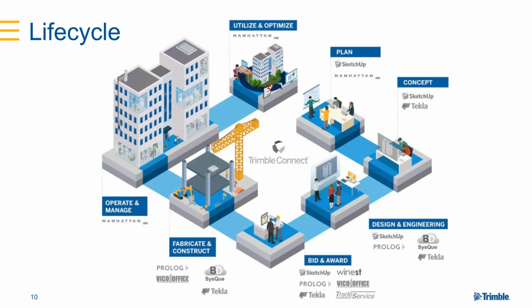So what I don't like about this slide, it fails to mention Trimble Access and Trimble FieldLink and the role of the surveyor. So I really want to stress the importance we as surveyors have in this project lifecycle. Before the design can even start, you have the surveyor on site collecting current topography or building as-built. Sometimes even during the proposal stage, you have surveyors doing some quick measurements or data collection for preliminary design. During the construction process, we are present for staking out and quality control and verticality checks and floor flatness and things like that. And then even in the building demolition process, you have a surveyor going in and measuring the structural elements, for example, to understand how you want to demolish and remove the building.